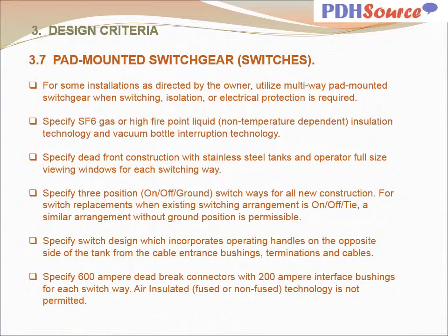Specify SF6 gas or high fire point liquid, non-temperature dependent insulation technology, and vacuum bottle interruption technology. Specify dead front construction with stainless steel tanks and operator full-size viewing windows for each switching way. Specify 3-position on-off ground switchways for all new construction. For switch replacements, when the existing switching arrangement is on-off tie, a similar arrangement without ground position is permissible.